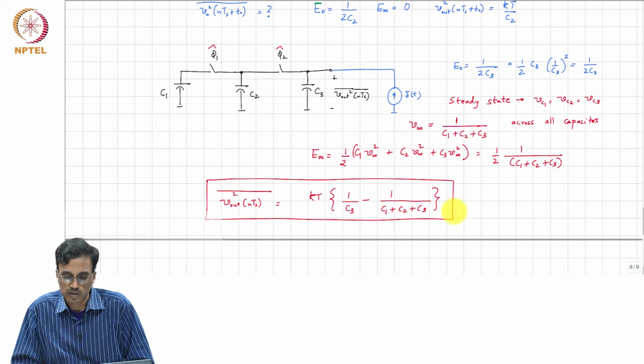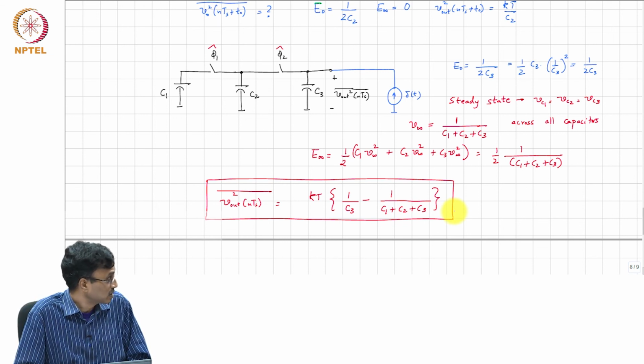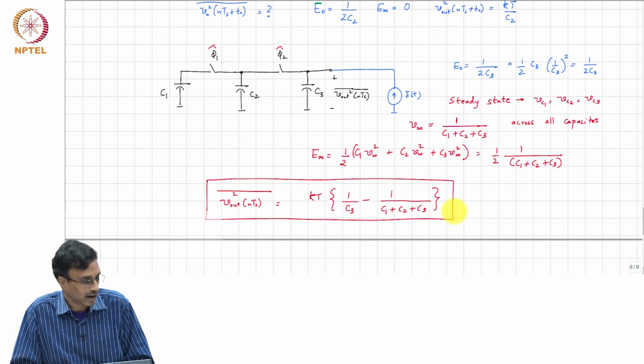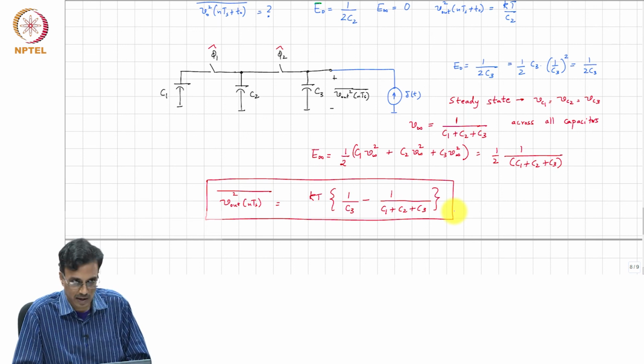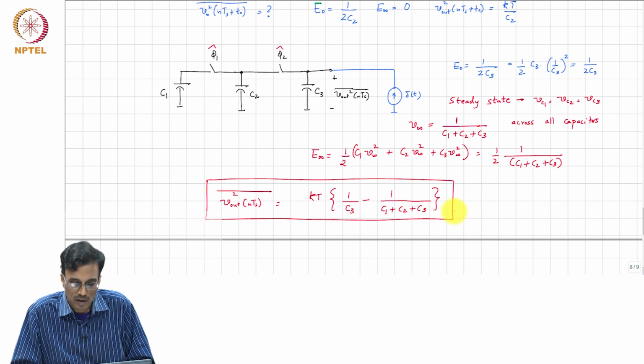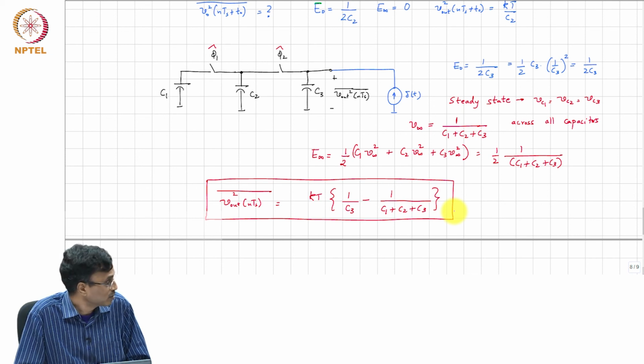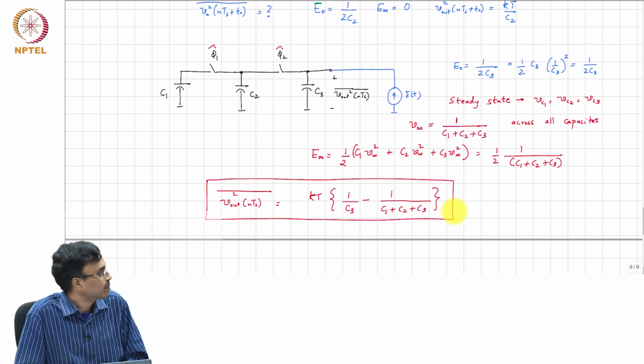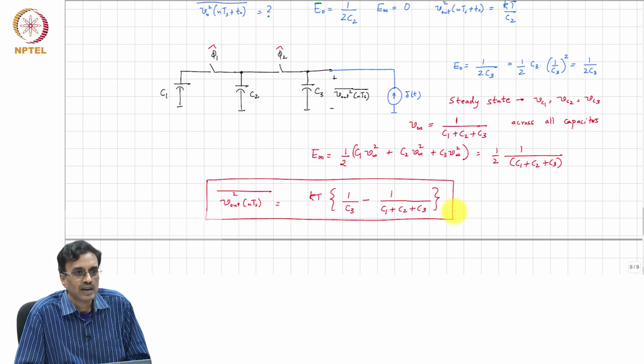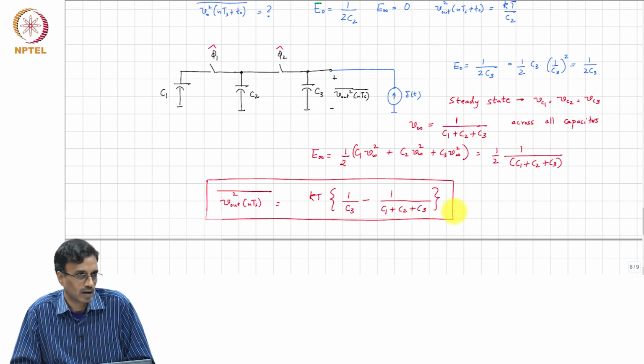Okay. So, thanks to this observation and energy conservation, just like how we saw in the case of linear time invariant networks, the process of evaluating the total mean square noise can be done by simply looking at the network, without calculating any transfer function at all, correct.